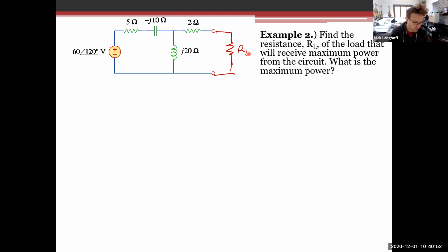So what we can start with is we know that the power is maximum when RL is equal to, now this is something that I did not focus on as much in the derivation, but if there's no reactive component to the load, then RL for maximum power is equal to the square root of R Thevenin squared plus X L squared.